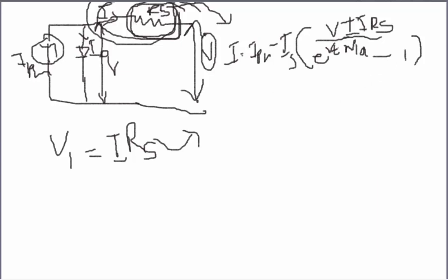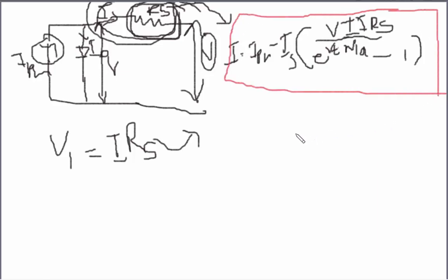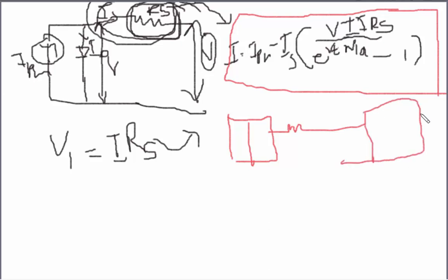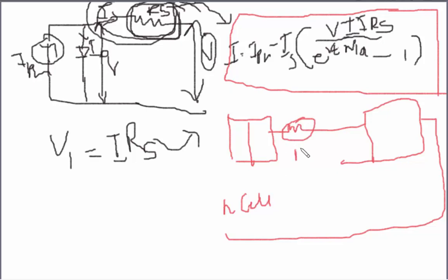This is the new equation with series resistance, because each solar cell contains some series resistance in order to prevent some currents. So all the modules contain n cells with one series resistance, because if I connect all the diodes in series, one series resistance will be sufficient. Now I will modify the circuit. Let's see.